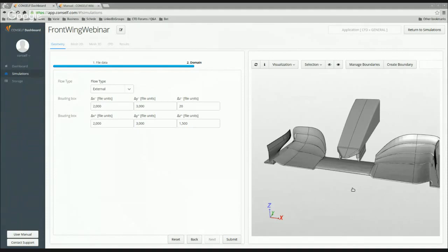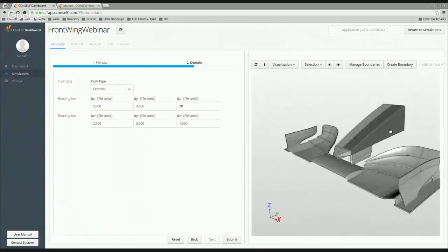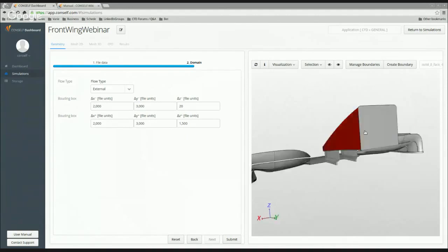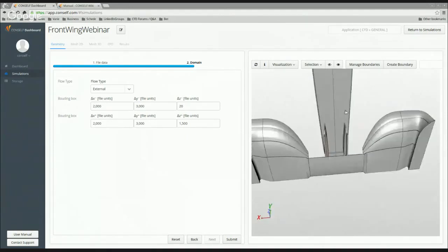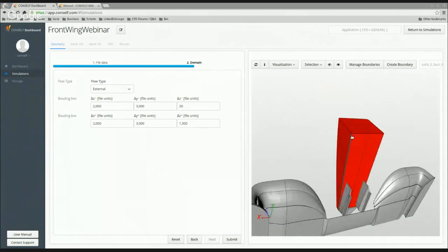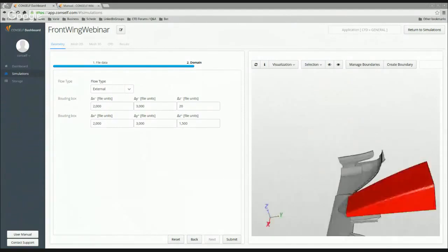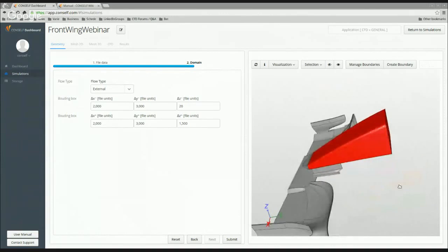As explained during the presentation, we need 3 different mesh refinements on this body in order to optimize solid dimension. And so first of all, I'm going to define the body that is this. The first boundary I'm going to create, I have to select every single face I want to add to the boundary. And so this is what I'm doing right now.